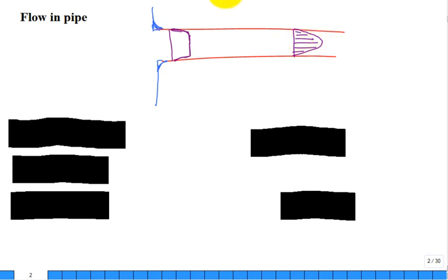Well, measure as a function of r going out from the center of the pipe. r goes from the center of the pipe to the wall of the pipe. Let's call that capital R. And when it's fully developed, you'll have a quadratic. If it's laminar flow, it'll be quadratic. It'll be a nice shape. But it takes a while for it to become fully developed.